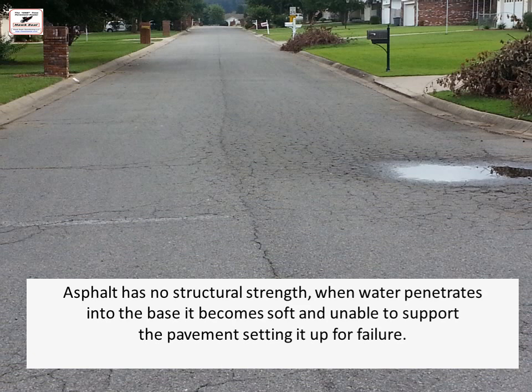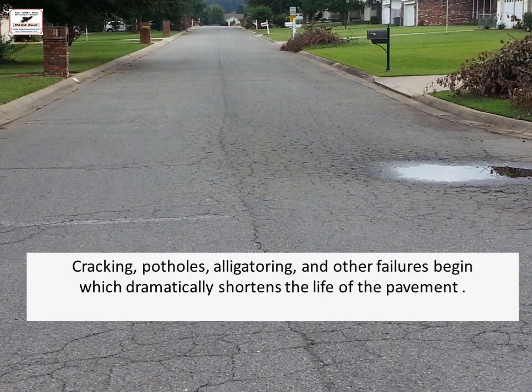Asphalt has no structural strength, so when water penetrates into the base, it becomes soft and unable to support the pavement. Then traffic forces the pavement to crack and fail. Cracking, potholes, and alligatoring and other failures begin when that base gets softened, and that dramatically shortens the life of your pavement.